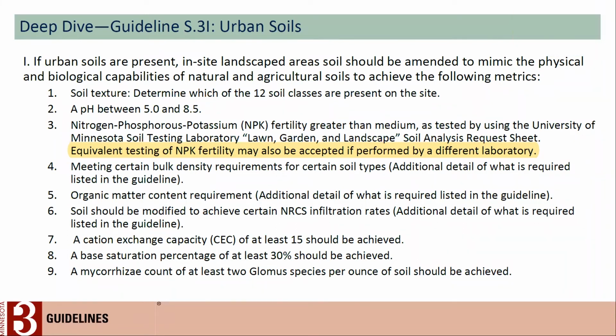So type C soils and the request for having a 30% infiltration rate is to use all available space outside the building footprint, including the parking lots. There are many different technologies available for infiltrating that amount of water through pervious paving, underground cisterns, etc. So that's the idea of that.